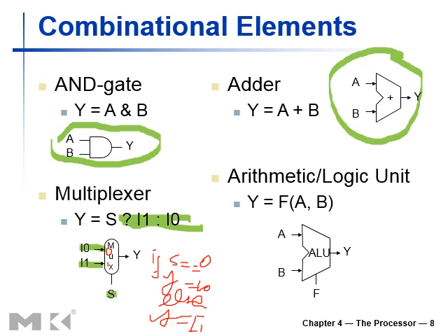Okay, so we've got multiplexer modules in our system. Then we've got some arithmetic and logical modules, for example our ALU. The ALU will receive the inputs A and B, and Y is the output, and this F is the control lines, the control signals. These control signals define which sort of operation our ALU is performing, and that is dependent upon the instruction itself.